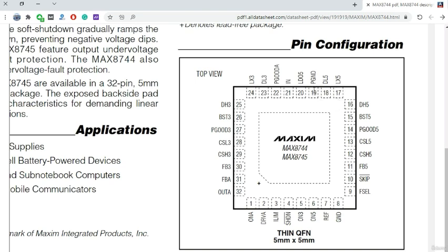Here we have the Vin. This is the Vin for this IC. Always the input power is 19 volt. For power management ICs, the Vin is always the same voltage as the power jack. For this IC, it is 19 volts. We will check this on the motherboard using the multimeter.